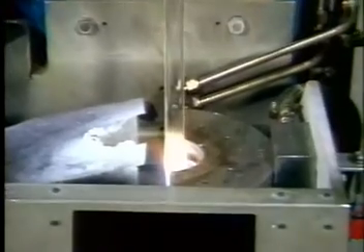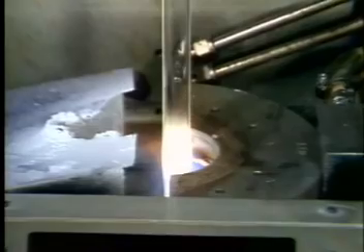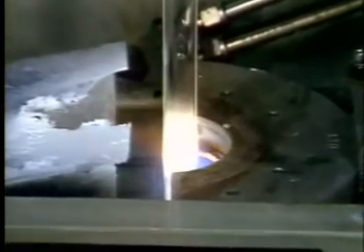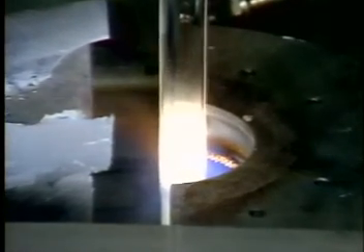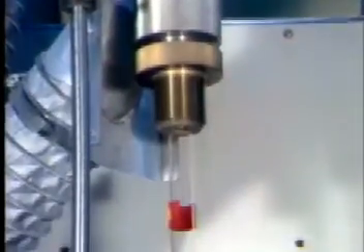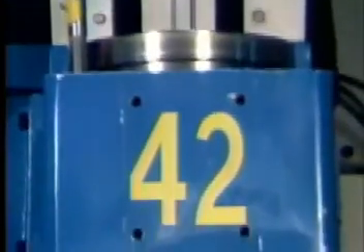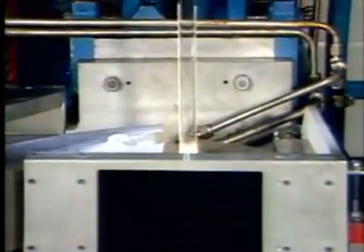There are a number of methods used to make glass optical fiber, based on the chemical vapor deposition process, or CVD. With the inside method, ultra-pure silica, germanium, or other elements are vaporized and applied to the inside of a silica tube heated by a hydrogen flame. Each pass of the heat source fuses a small amount of raw materials to the inside of the tube as a thin layer of glass. The composition of the vapor is designed to create layers of glass with a refractive index usually higher than the silica tube.